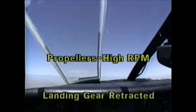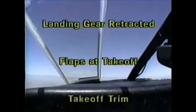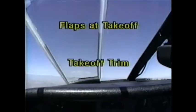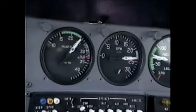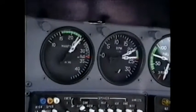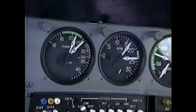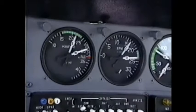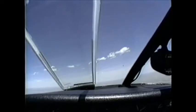The proper configuration for the demonstration is with the propellers set to high RPM, the landing gear retracted, both the wing flaps and cowl flaps at the takeoff setting, and the trim set for takeoff. Establish the airspeed at VYSE and reduce the power on the critical engine as recommended by the manufacturer. Smoothly increase the pitch attitude to bleed off airspeed as you add climb power to the operating engine. Establish a 5-degree bank toward the operating engine and maintain the heading with rudder pressure.